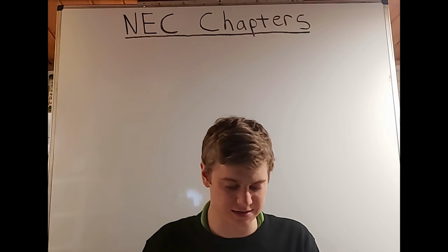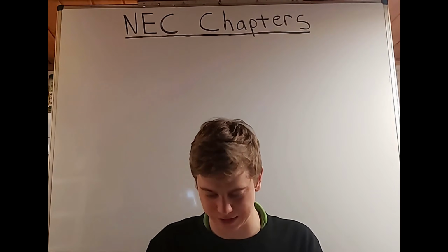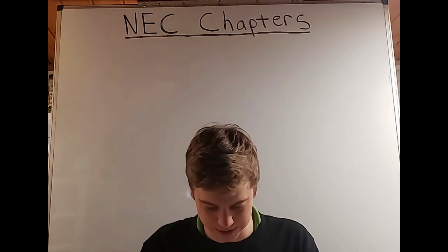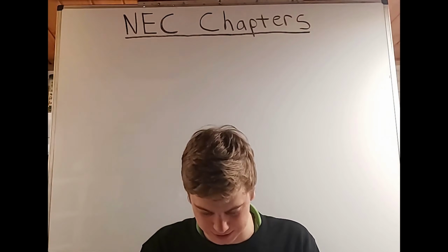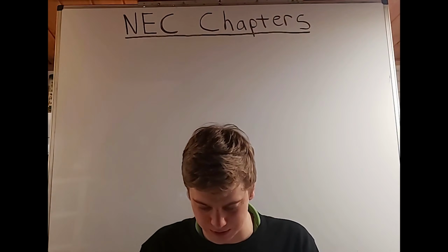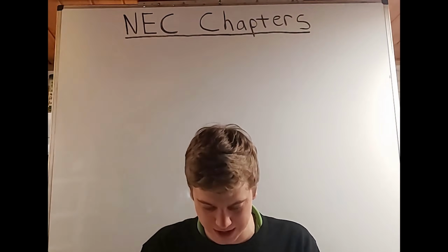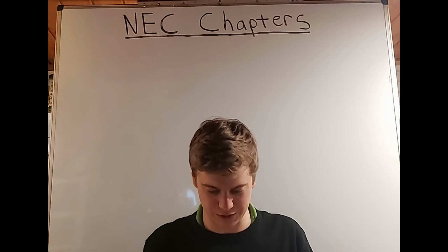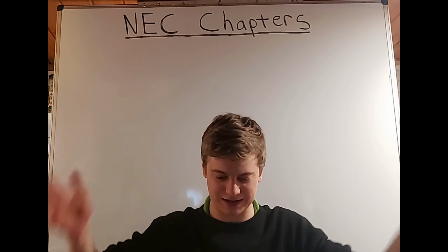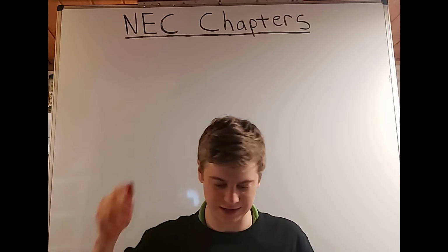2, we have islands and peninsular countertops and work surfaces. We see A, we need at least 1 receptacle to be provided for the first 9 feet of the countertop or work surface, and a receptacle outlet shall be provided for every additional 18 feet of the countertop or work surface. Okay, it's really weird, but what it's saying is if you have an island up to 9 feet, then you need at least 1 outlet.